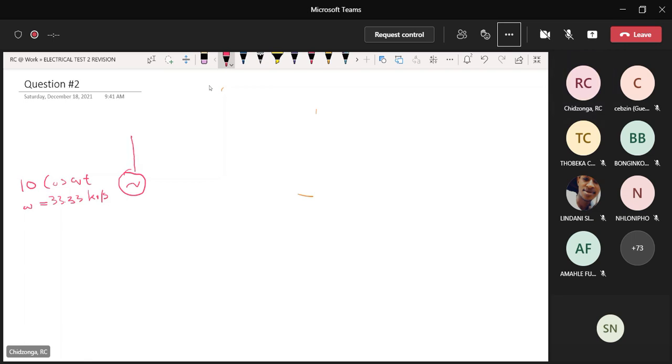And then the first arm has got an inductance 15 millihenry in series with 500 ohm resistor. So that's an impedance, right? So it is R plus J omega L. If you put this frequency in kilo, right? 33.33 kilo times 15 millihenry, you'll see that is going to be 500. So this one I can write right away. That is the impedance. All right.